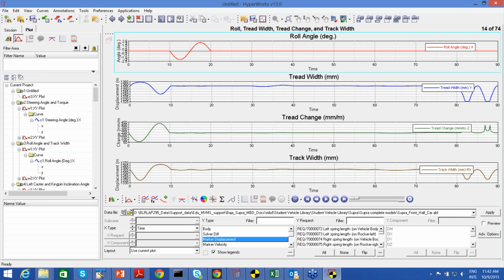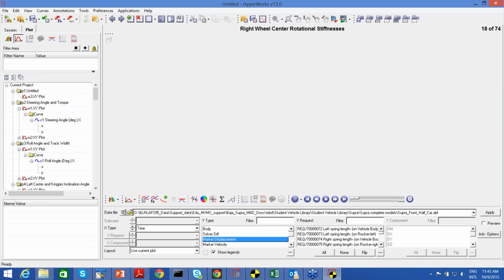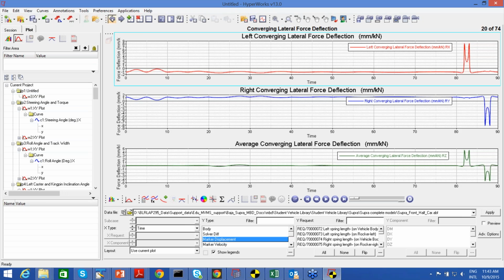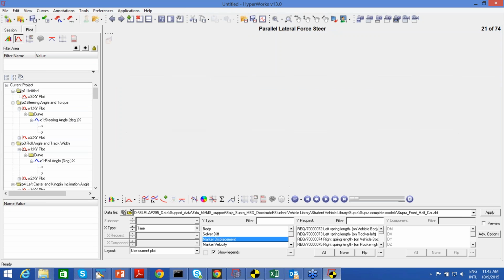And these are all the studies which can be carried out in the design stage of the vehicle. Once you get a good configuration of the vehicle through the dynamic events, then you can fix your design coordinates and carry on further analysis of the vehicle and the component levels after extracting the loads from the MBD simulation. So these are the standard outputs which you can easily refer to offline also while performing these events.